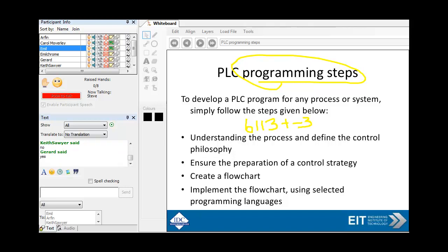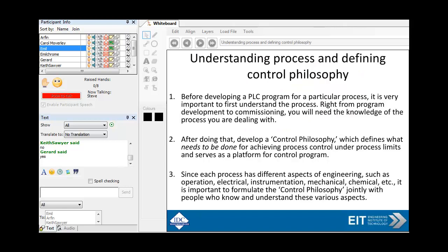Okay, this is like a C++ programming standard. It's a standard for all PLCs. So the idea is that any reputable manufacturer, and believe me, most manufacturers are jumping in using the 61131-3 standard. So there are different types of programming languages. You could go from Ladderlogic, which we're all familiar with, to function block, to instruction list, to flowcharts. They all are defined by the 61131-3 standard. So it's an attempt to try and unify programming.